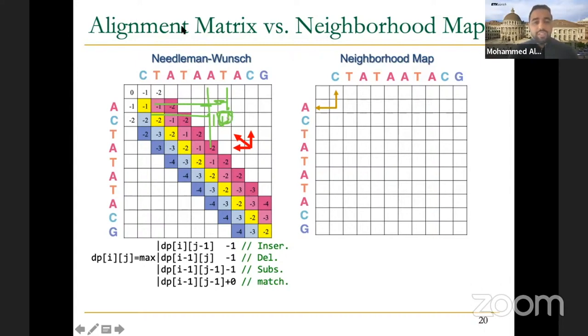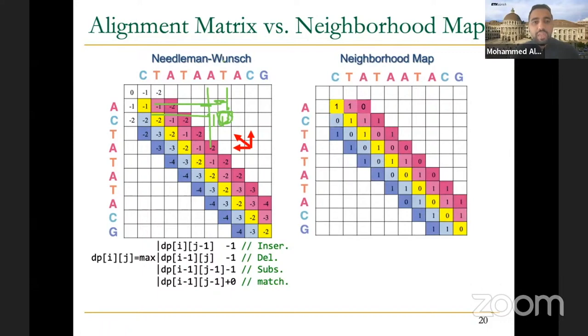However, in our calculation, or in GateKeeper, there are no dependencies at all. Why is that? Because you just compare the A with the C, A with the T, A with the A, and so on. So everything is totally independent, because when you shift this sequence by one step and then compare with the other sequence, that is totally independent. So you can do it in one operation in the FPGA, for example, or in one SIMD register, you can load everything over there if it fits in 256 or in 512, depending on what kind of SIMD lane you are using. If it fits, then you can do it in one cycle, right? Because everything is independent, and you can do it for all vectors together in parallel.